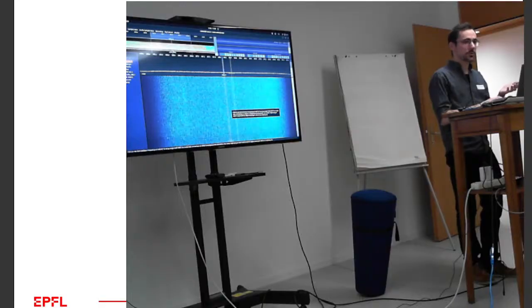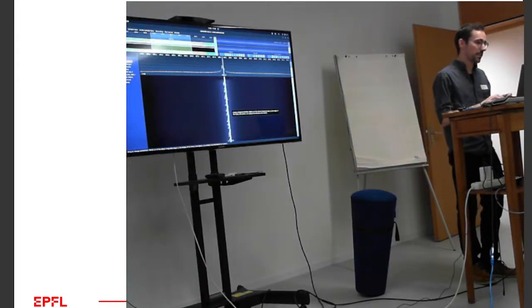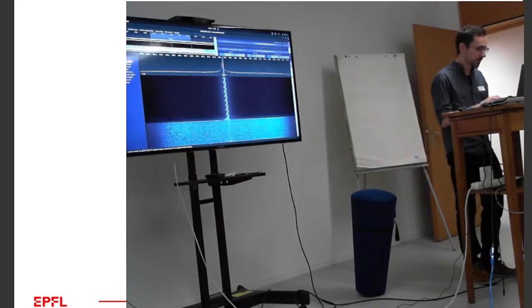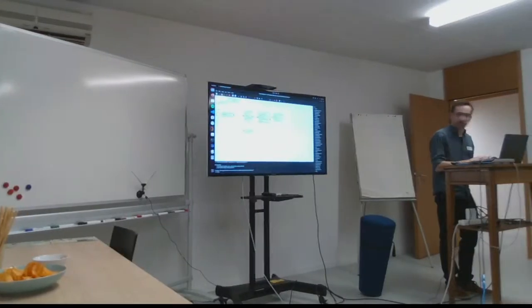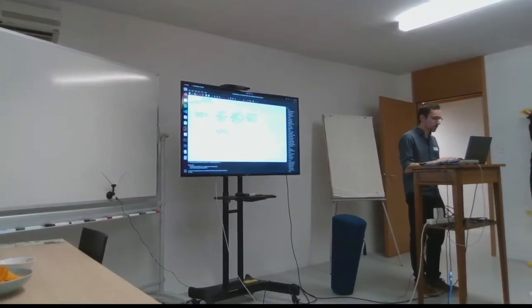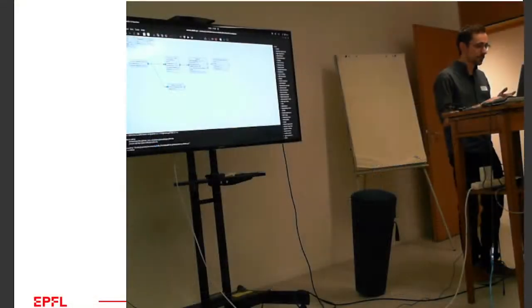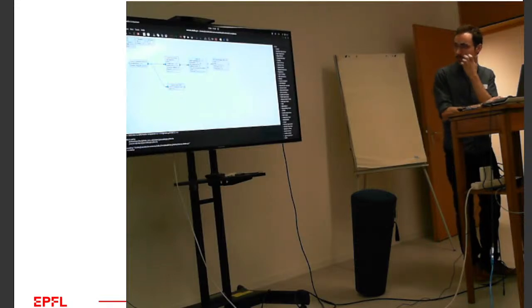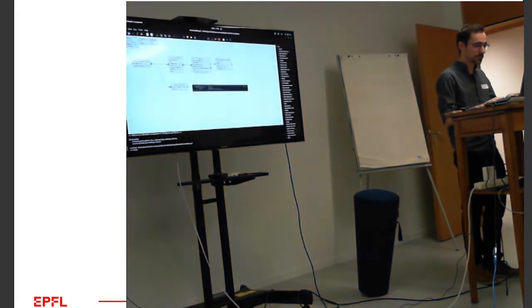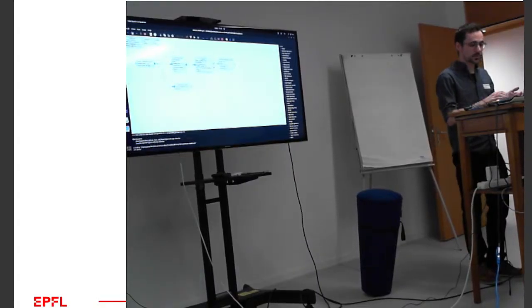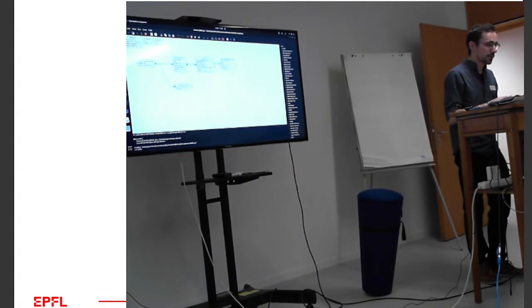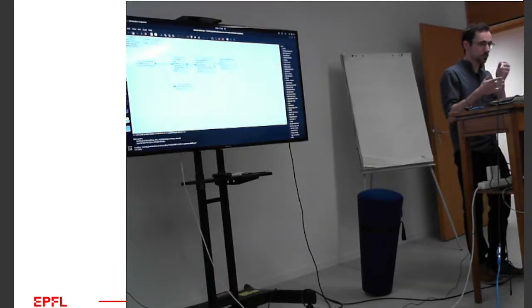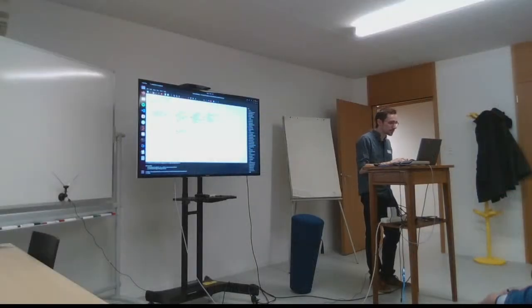Now this software demodulates FM and AM, I think, but it's not planned for LoRa. So for that, we can move to GNU Radio. And here is a simple flow graph that I made for a receiver. You get the block that we made, that I mentioned before, with the different parameters for the reception. The LimeSDR source, that's just to say I want to use this radio. Then a low-pass filter, that limits the bandwidth we want to use, and it's just there because I want to plot it in a nice way. But if we start it,